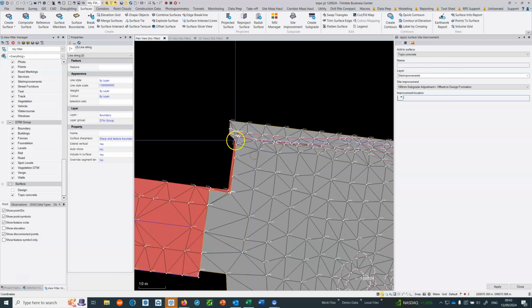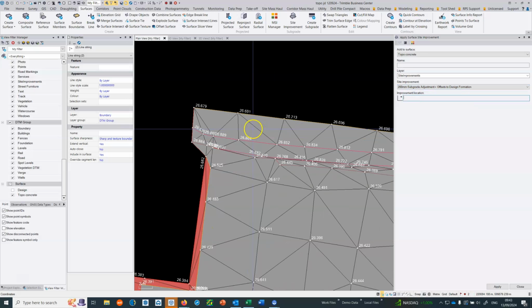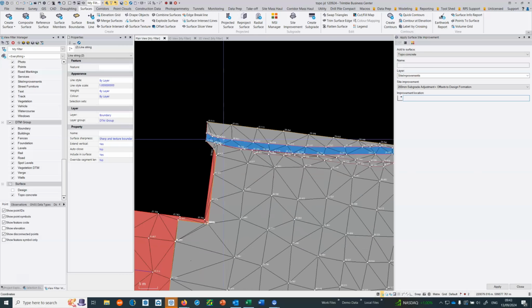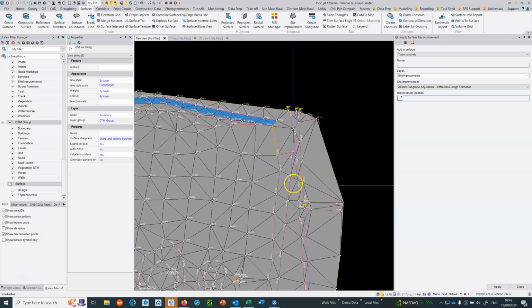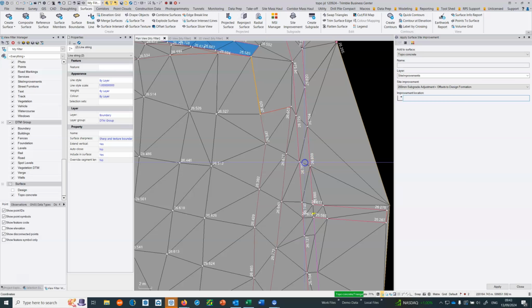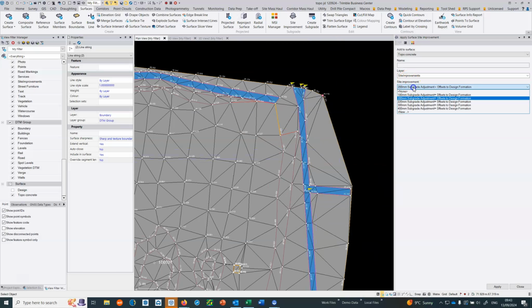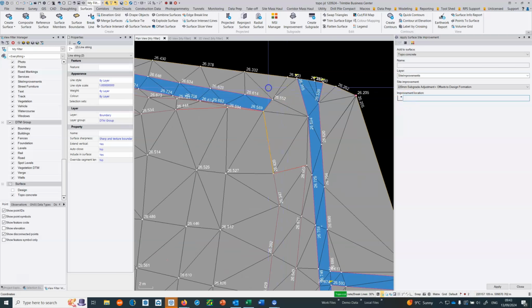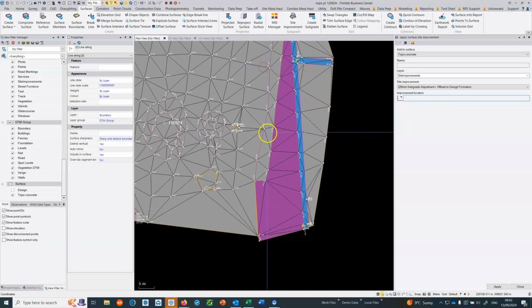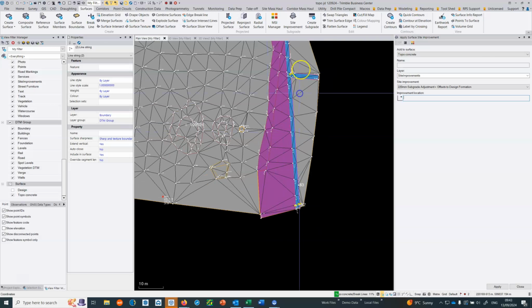So these are all areas where that's a 180 offset to the bottom of the concrete after it's been stripped out. This is a road that's got 200mm strip coming out of there. So we're just going to put in that, and again it floods out until it hits the lines. Same with the footpaths. And then we've got topsoil areas that are being stripped out here. So we just tap in here and tap in here and in here.